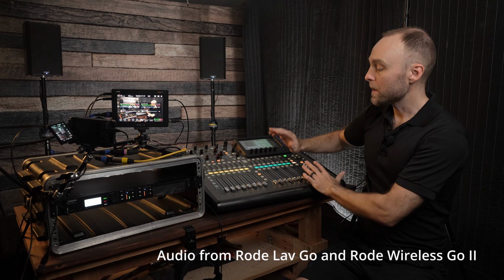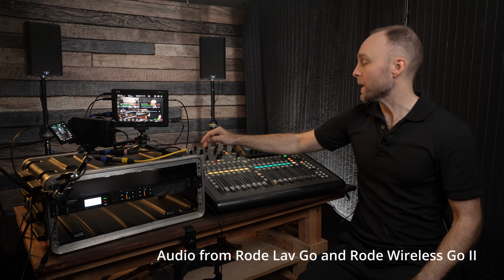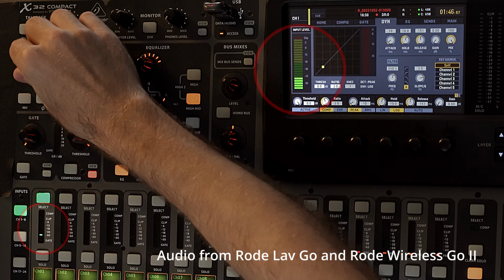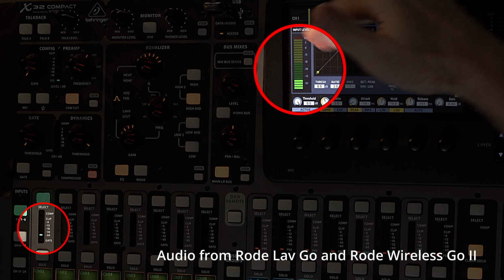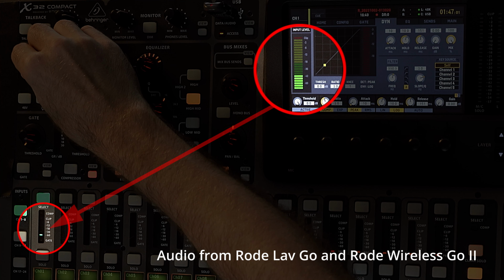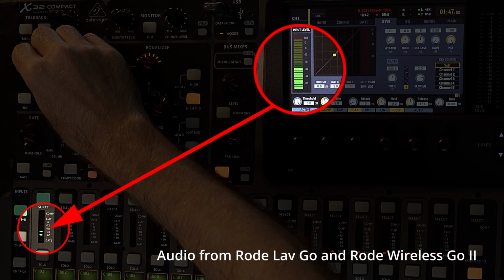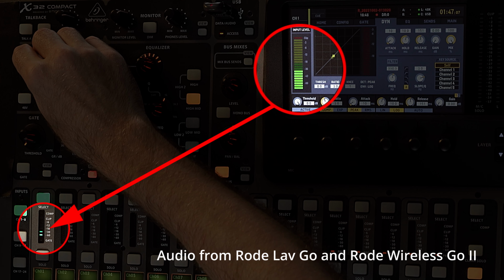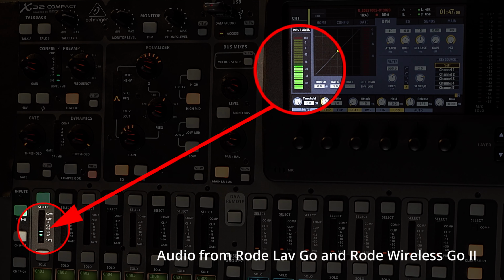All right, so at the console, I'll leave my faders down for a minute. I'm going to gain structure my input visually here. Check 1, 2. We can already see without touching the preamp from before, I've got much stronger level in here. So I'm going to go ahead and gain this up with my eyes. Hitting about negative 18 on average here, negative 18 dBFS.